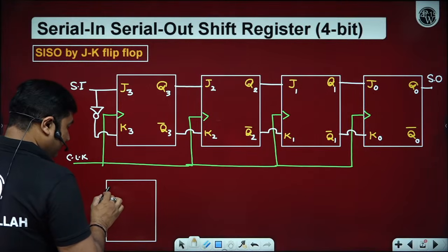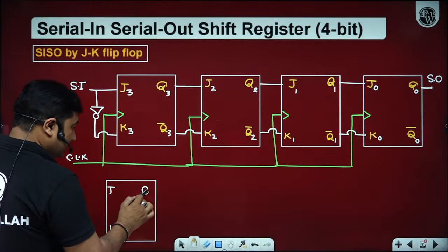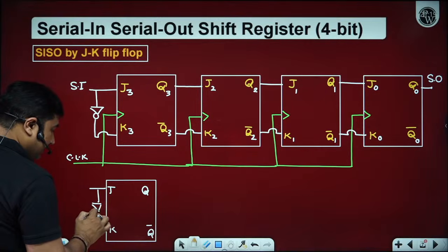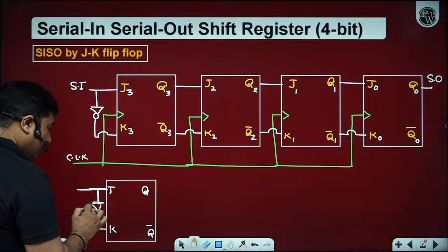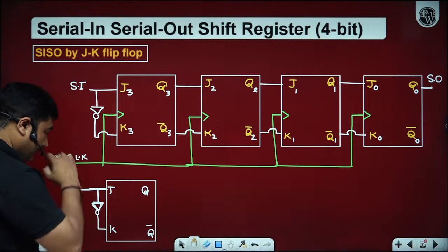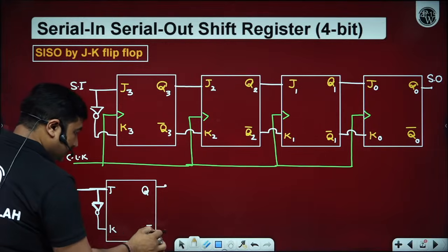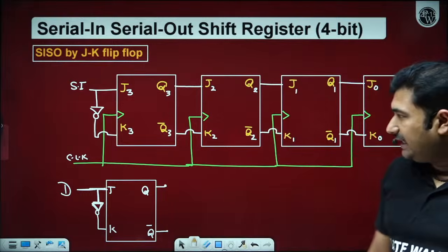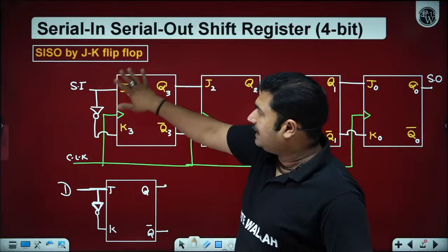By using a D flip-flop, can I make a D flip-flop from the JK flip-flop? In the last lecture, we studied how to convert one flip-flop to another, or how to design a desired flip-flop. So for a D flip-flop using a JK flip-flop, in the conversion we saw J equals D and K equals D bar. So can you observe this flip-flop as a D flip-flop?